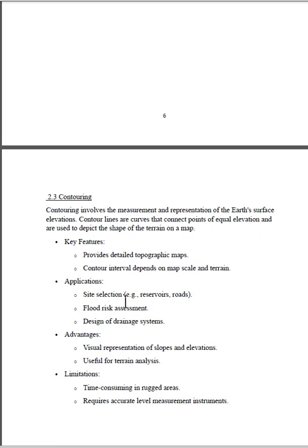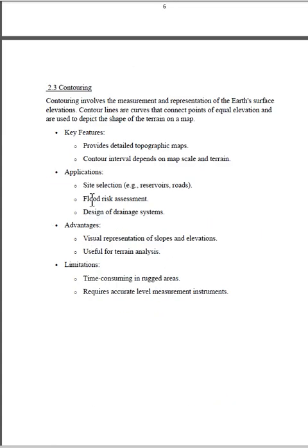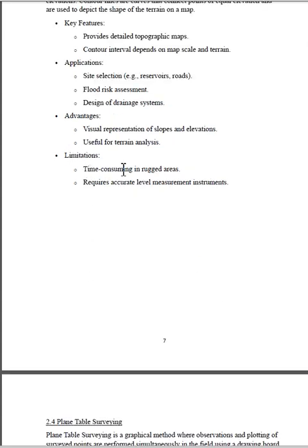Applications: site selection, reservoirs, roads, and etc. Flood risk assessment. Design of drainage system. Advantages: visual representation of slope and elevation, useful for terrain analysis. Limitations: time consuming in rugged areas, requires accurate level measurement instruments.